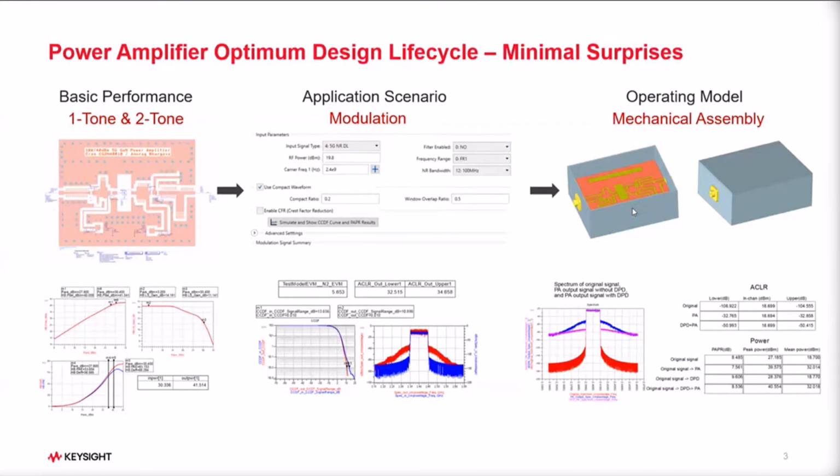And if you have done RF microwave designs, you might have seen this is the place where you see a lot of surprises. When the chip folks measure on-die performance, it comes out excellent. As soon as they package it and test the package mounted on a PCB, the performance might change, even leading to oscillations.